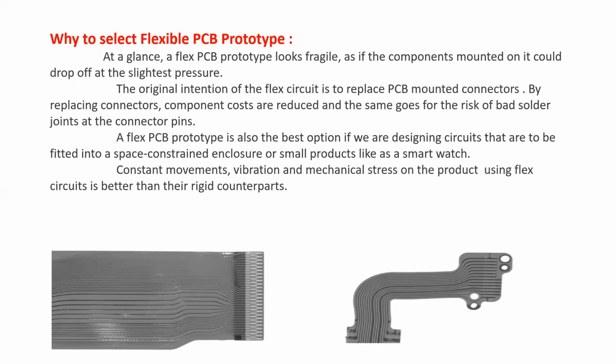Now let us see why to select flexible PCB. We can compare here the rigid PCB and the flexible PCB. The original intention of the flex circuit is to replace the PCB mounting connectors. By replacing these connectors, the component costs are reduced, and the same goes for the risk of bad solder joints at the connector pins. Sometimes because of movements, vibrations or mechanical stress on the products with normal PCB, there may be loose connections of the components or the connectors. This will be avoided in most flexible PCBs.